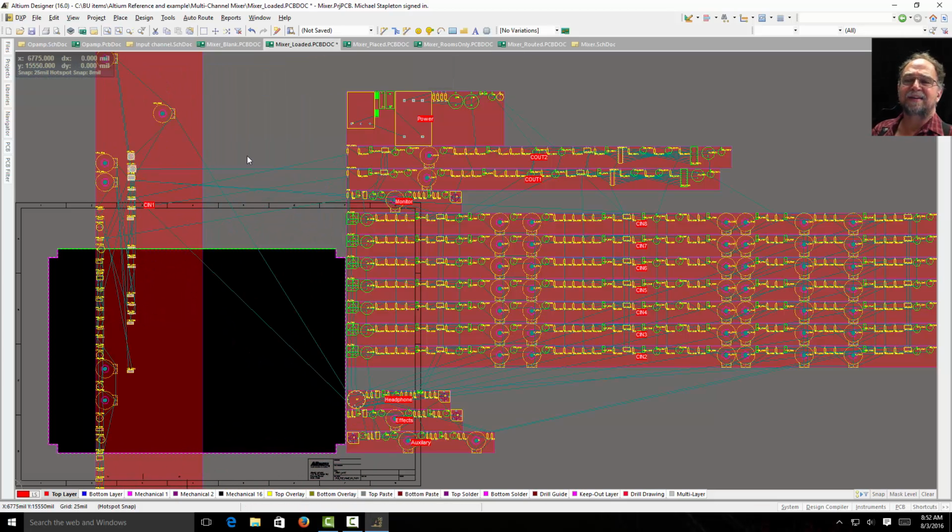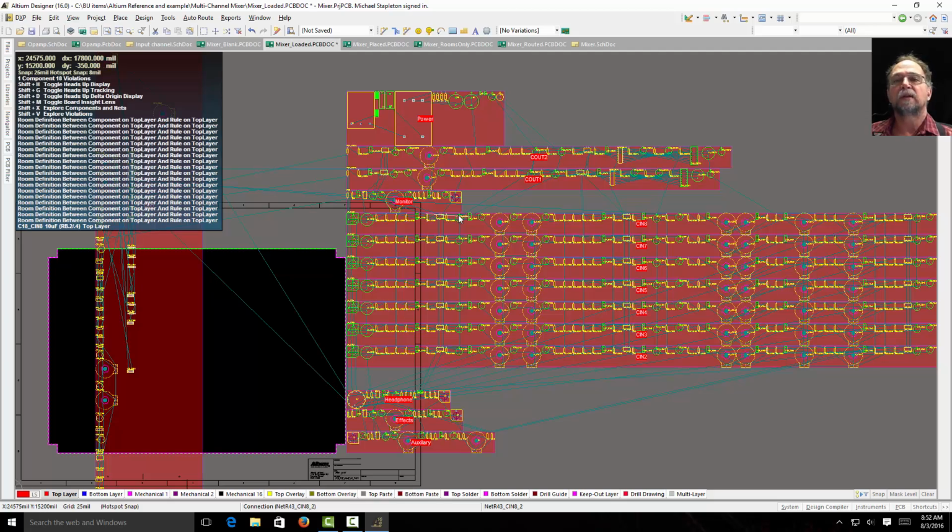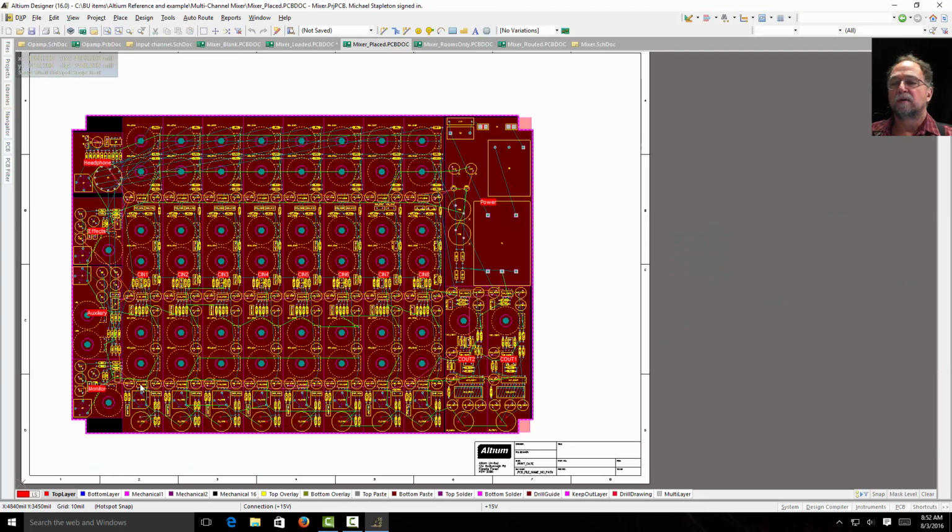Now, once I've done that, I can tell Altium to look at this room and make all these rooms look the same. And that's what they've done here. They've taken one room right here. Here's a channel in. It says right here, channel in 1. They've placed all their parts exactly where they wanted them. And they came up and they told Altium, hey, look at this room and make these other 7 rooms look just like this room. The advantage there is I only had to do one, right? I only had to do one schematic, and I told Altium to repeat it.